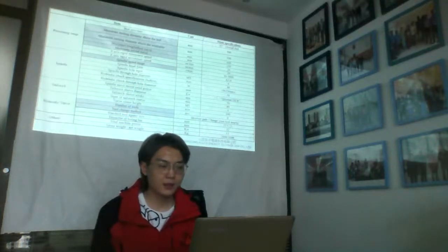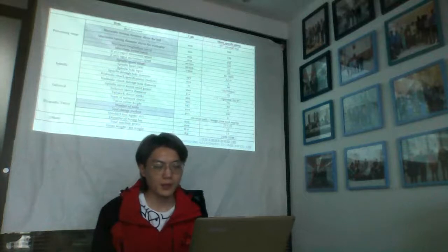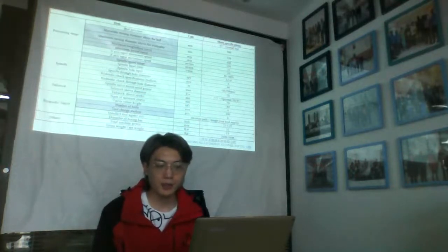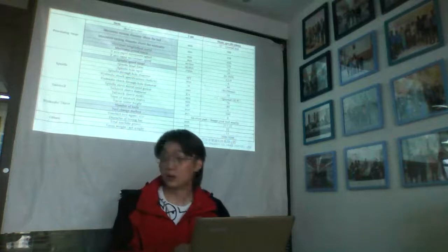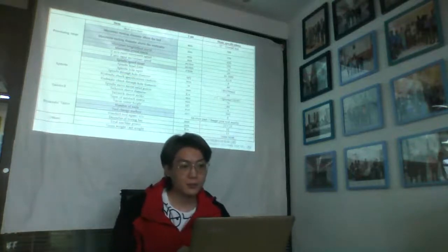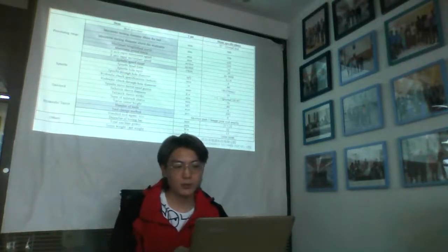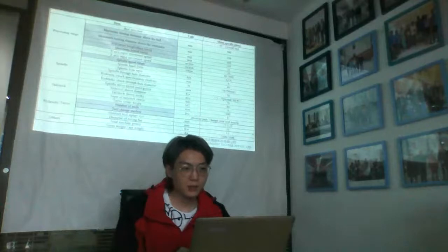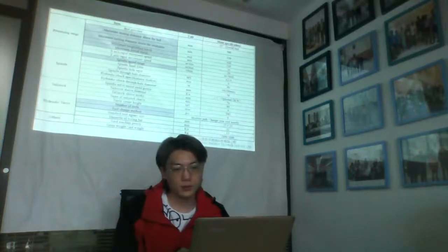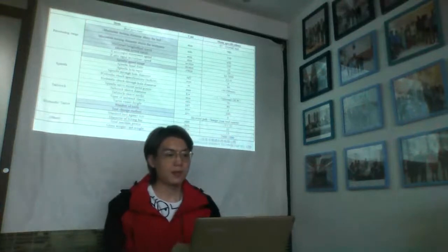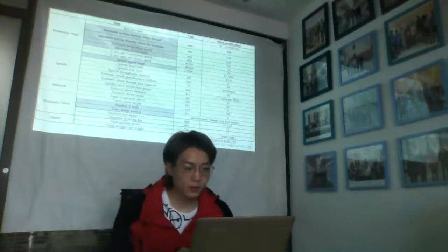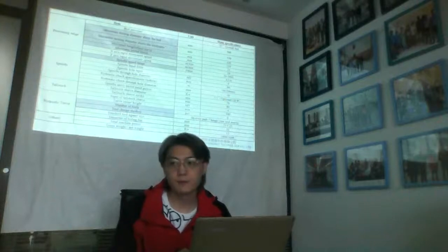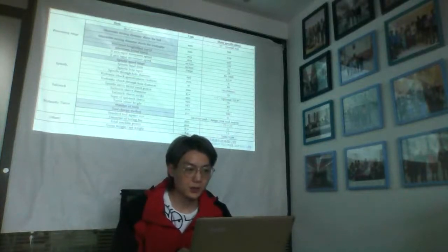The maximum turning diameter above the bed is 580 millimeters, and the maximum turning diameter above the work table is 330 millimeters. The maximum longitudinal travel is 450 millimeters, and the maximum lateral travel is 250 millimeters.